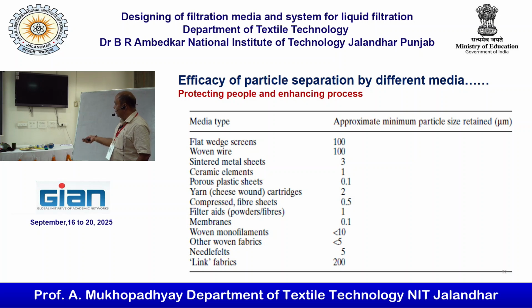Membrane can separate the lowest size of particle, 0.1 micron as you see over here. Again, it depends on the membrane. Several membranes are available, but the typical size could be 0.1 micron, and particles below 0.1 micron can be separated by membrane. So different types of filter media are there, and their capabilities will differ depending on the application. We can choose the right kind of media.